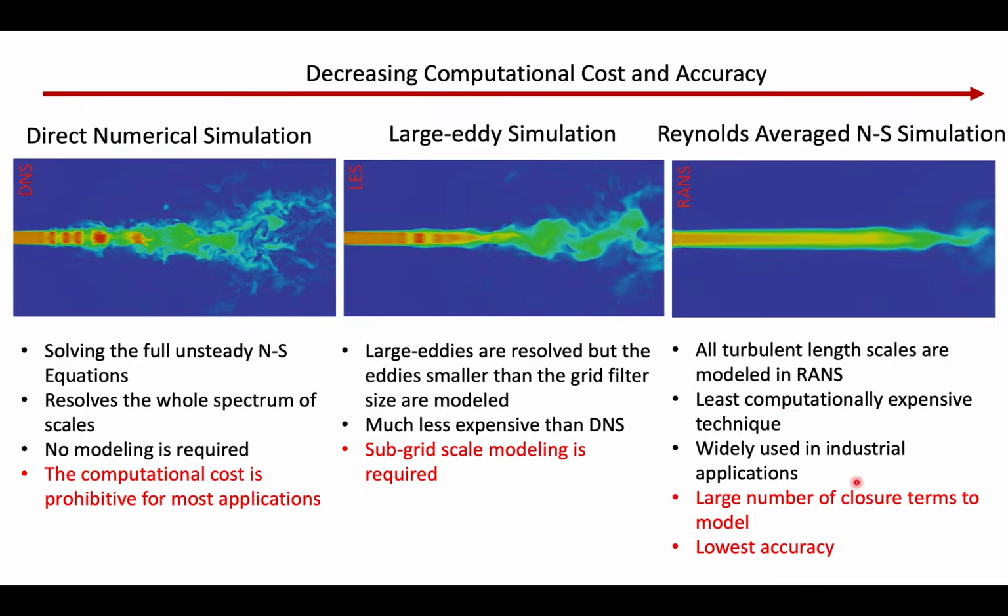Most of the commercial software that you see, like ANSYS Fluent, uses this RANS method because it's very, very computationally cheap, and also it gives the mean flow right. So it's actually what is mostly needed for many engineers. That's why it's very commonly used in the industry.